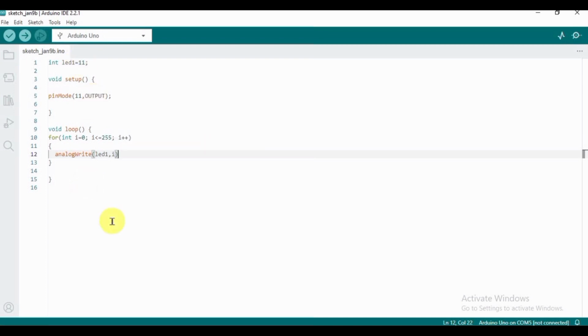So I'm calling this pin number 11, and here I am inserting a time delay of 12. So this is basically PWM, where we can control the time delays. We are going to use some different time delay. And now it's time to write the second for loop, and I have already described we are going to write this loop for decreasing brightness.